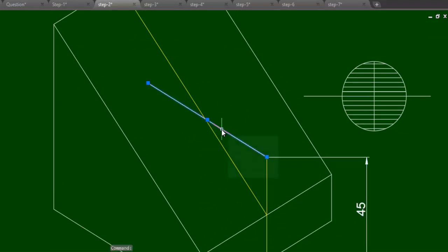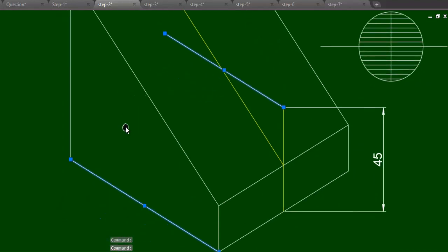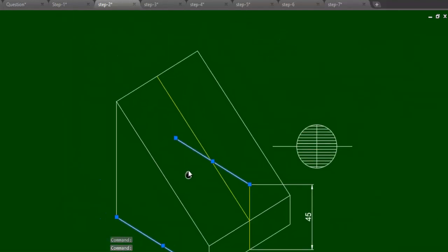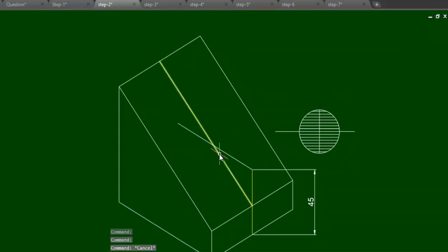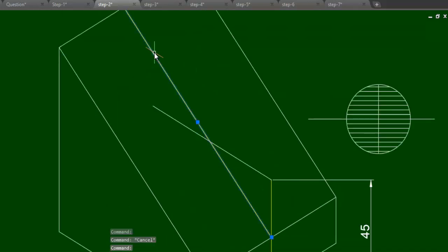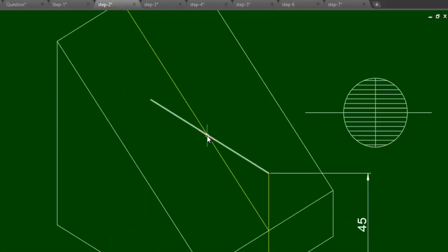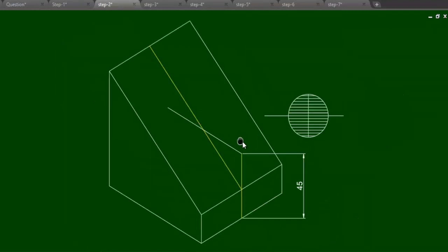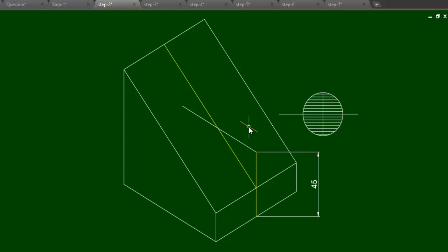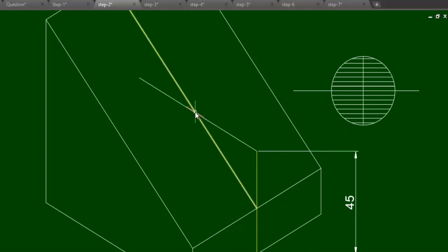Now this line is an isometric line, parallel to this line, a 30-degree line, so that it will intersect this inclined plane line. You can draw like this. Just extend it, whatever the length may be, so that it will cross through this. So we will get this particular point, the intersection point. Now it is the center of the circle on this inclined plane. I will later explain the practical aspect of this. Actually, we are trying to create the shadow of this center on the inclined plane.